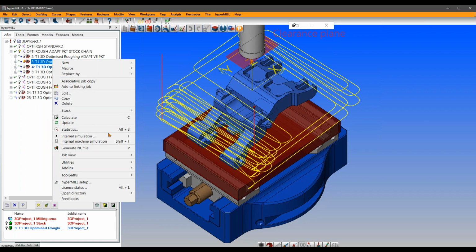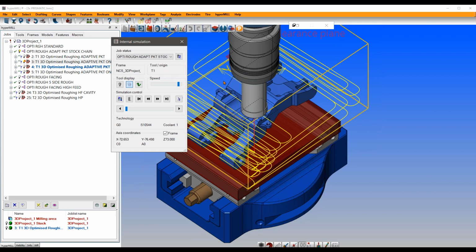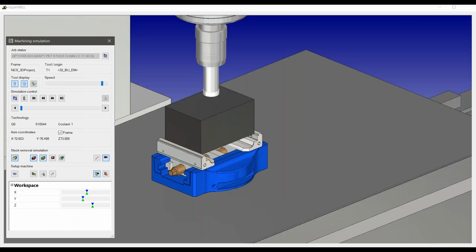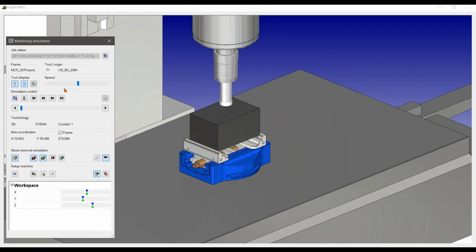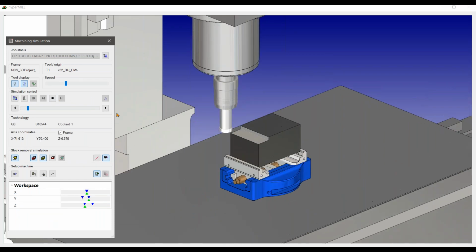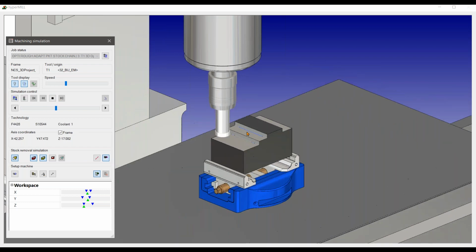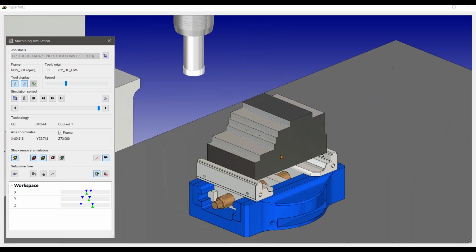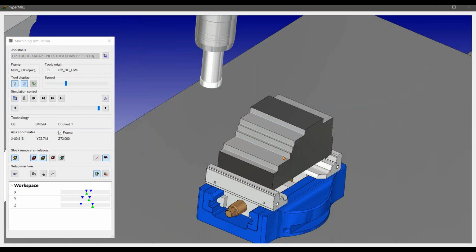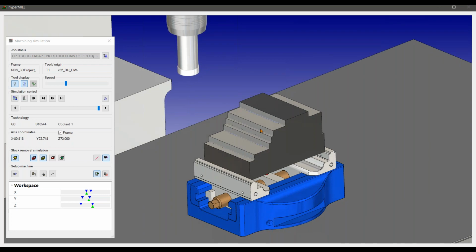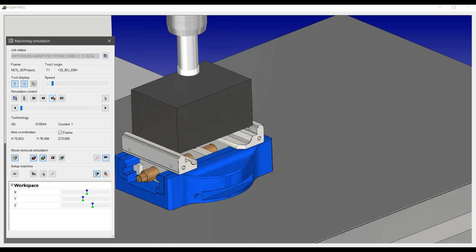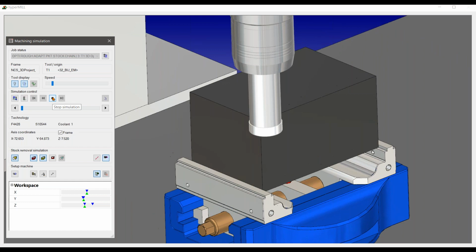I have a scenario here. So let's just start the simulation a little bit differently. You see the toolpath. It's slabbing or peeling off at the moment and working its way into the center. What it's done is made sure it's removed the bulk of the material in straight line fashion, and it's focused on no detailing.